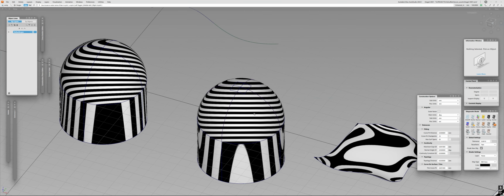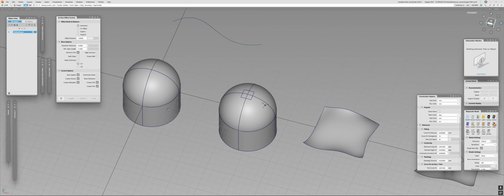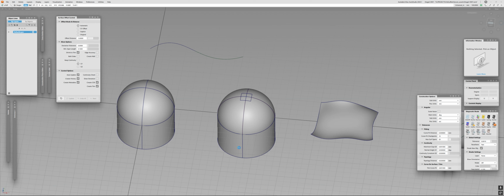But in return, now we have more surfaces when we need to create a thicken command, or basically create an offset to this. We will have even more issues. Why was that? Because we have more surfaces and we have trimmed surfaces. So basically we have a mask on our surfaces which masks part of the domain of the surface. And the surfacing tool, the offset tool, is supposed to account for these nuances as well. So let's see how it does. So I will go into the surfaces and I will go with automatic. I always start with automatic, actually.